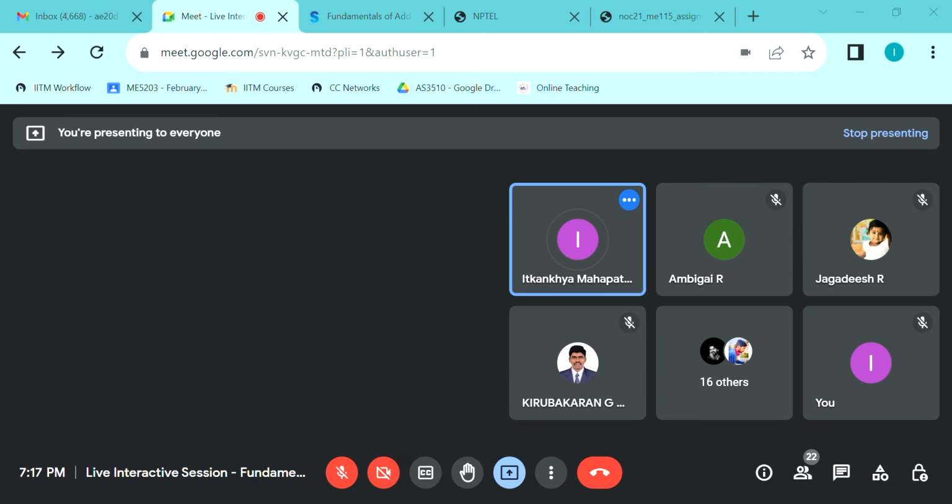Okay, so sheet lamination. Since someone asked what this is: there is a material spool, and from the material spool the sheet material goes to the build platform. From a motorized mirror a laser comes and hits the sheet material on the build platform, where pressure and temperature are applied, through which the sheets are laminated. So this is just the overall gist of the sheet lamination method.